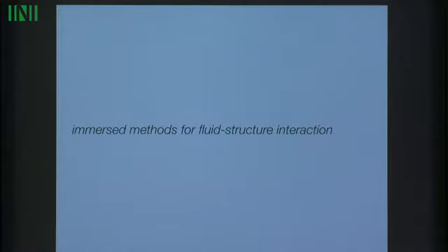So the methods that we use to do dynamic simulations of valves are a little bit different from traditional computational mechanics methods for doing fluid-solid interaction. Heart valve leaflets are thin, elastic structures. They're immersed in fluid, and they're thin. They essentially move with the flow that they're immersed in, but at the same time they generate forces, and those forces are applied back to the fluid, and they influence the fluid motion.